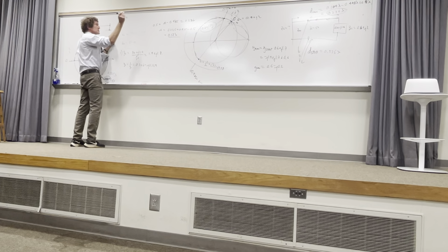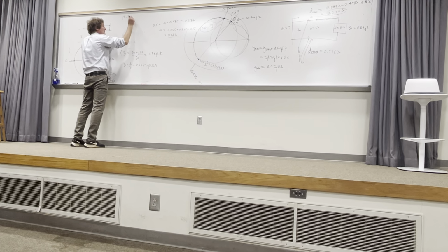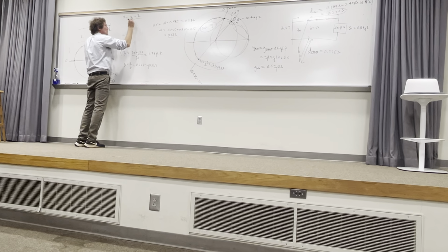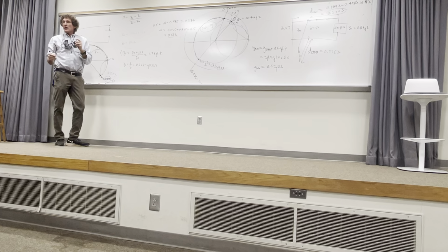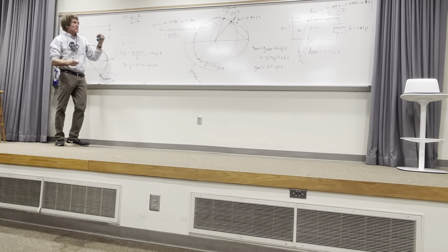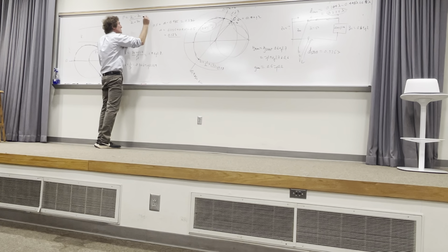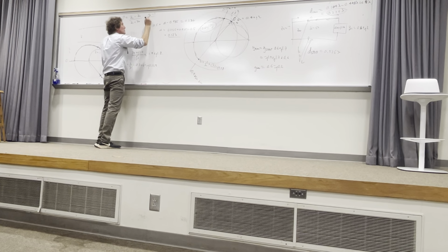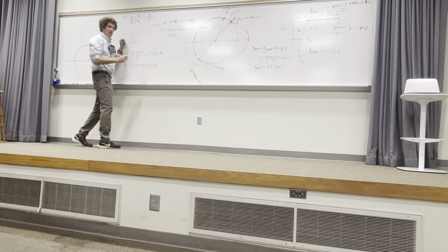I just want to make mention of this. It is Z that I'm going into, Z load or Z whatever that is, minus Z naught over ZL plus Z naught, correct? Now, if I divide by Z naught, top and bottom, I simply get normalized ZL minus 1 over normalized ZL plus 1, correct?